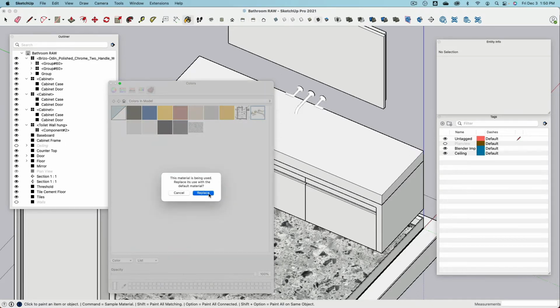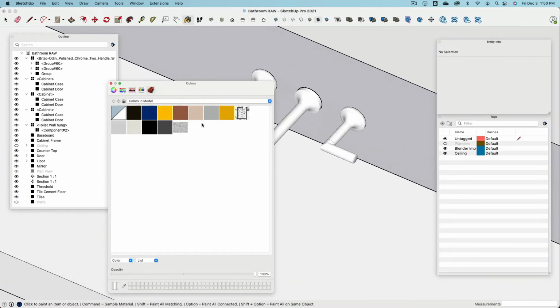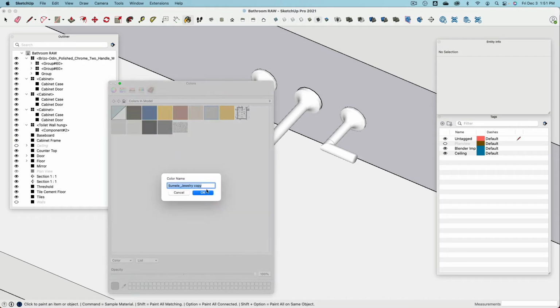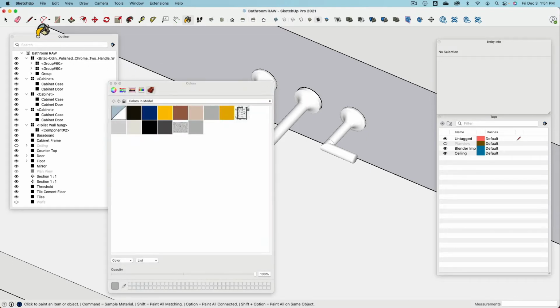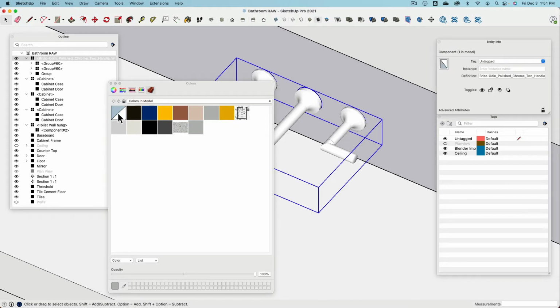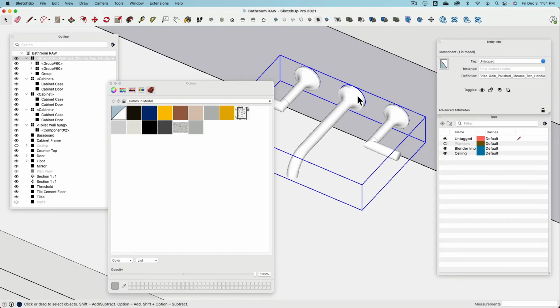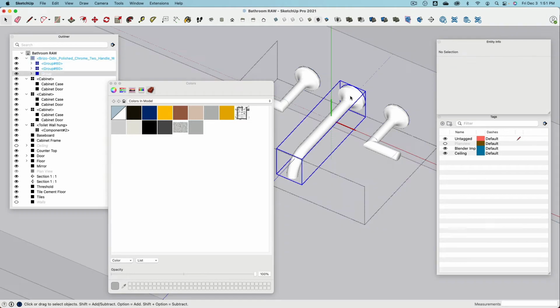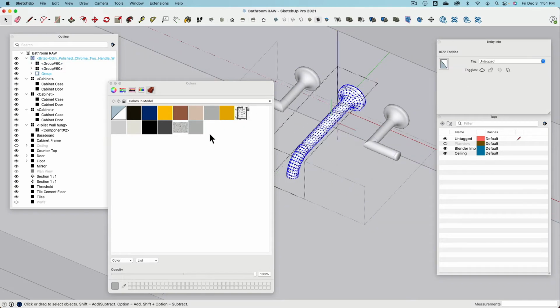Now, if we would like to give this a nice material, let's say we say new texture. But it shouldn't just be a texture, it should be something just white. Duplicate it here. We call this Chrome. Okay, and then you never want to add a material in group mode. That's a disaster. That's terrible. We want to only do this when we are inside the edit mode.